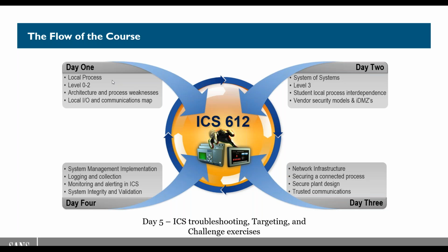As we move into day 4, more focused on system management. Lots of questions here, lots of capabilities that are coming into industry at this point, where we can look at doing logging and collection within the industrial control system environment, performing monitoring and alerting within an industrial control system environment effectively, and ultimately when things need to be checked for a potential incident or recovered after a fault or a failure, looking at ensuring system integrity and industrial control system device validation prior to reconstituting it.